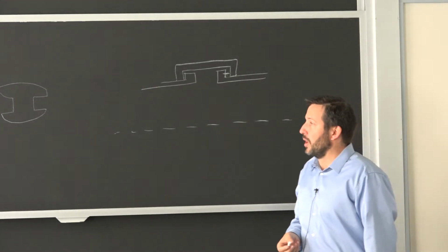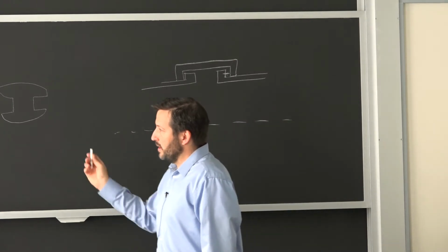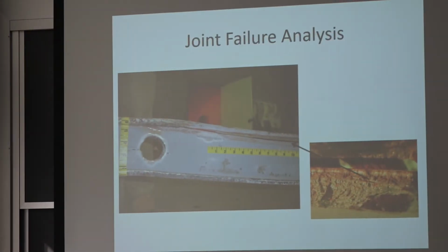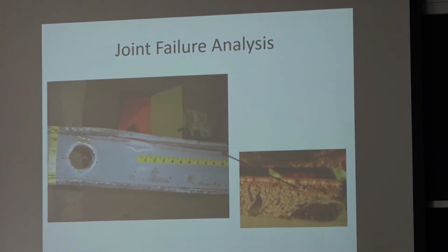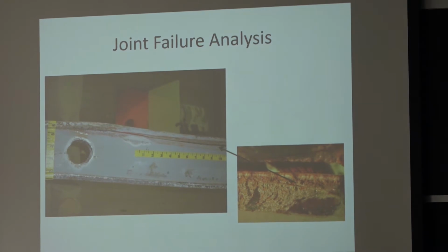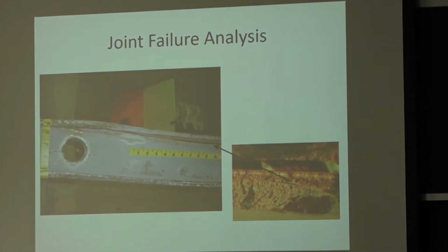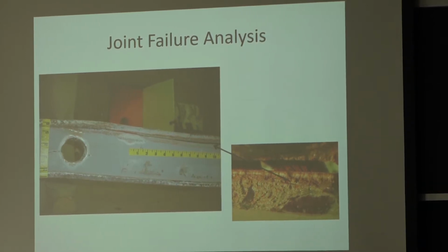Now, when we looked at it, the clamp was completely off, broken, and it would have been hard to look for this mark over 30 feet of diameter. It's just not practical. The shop was pretty dark. So it's really by looking at the fracture surface and knowing where it started to crack on the 30 feet that we just had the cylinder turn. And I looked closely here to see if there was anything I could find, and that's where I saw it. It was lifted.